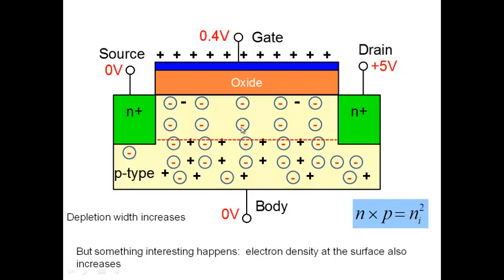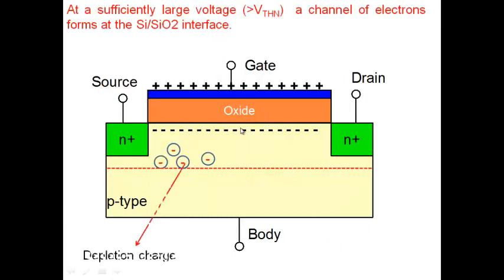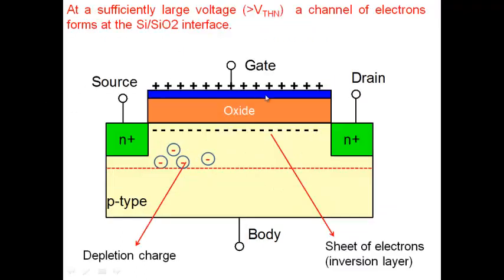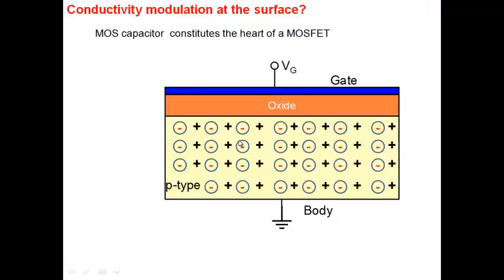So what is really happening is, let me look at it in a little bit more detail here. The heart of this MOSFET that you see here, this is basically a source of carriers, and this is for collecting, for making a transistor. The heart of the MOSFET is this metal, oxide, and semiconductor, which is a capacitor here. So metal, oxide here is a capacitor here.